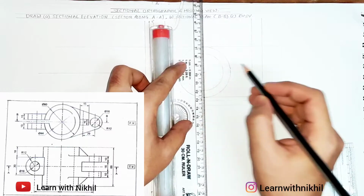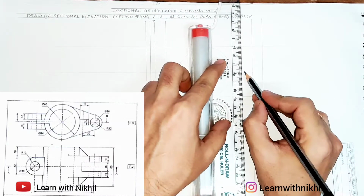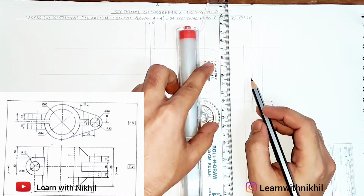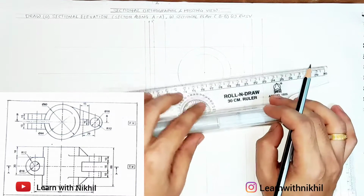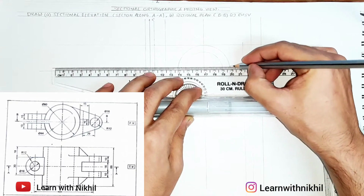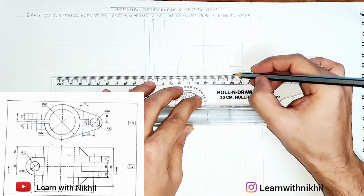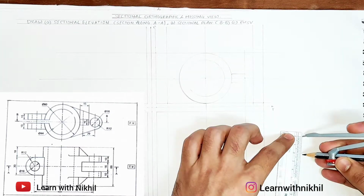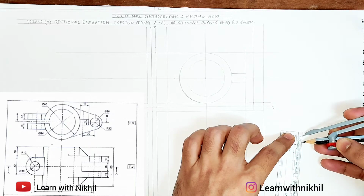So I marked a point 15 millimeters. I'll draw a line parallel through it, extending towards the top view. This is the slant line. From the front view, it looks straight with thickness as 10 and length as 15.